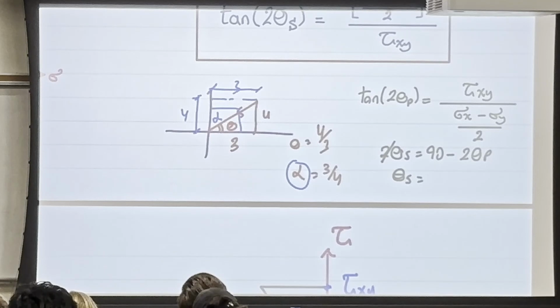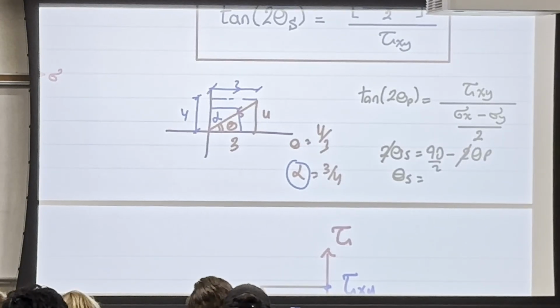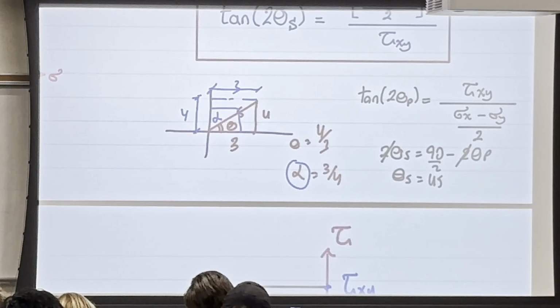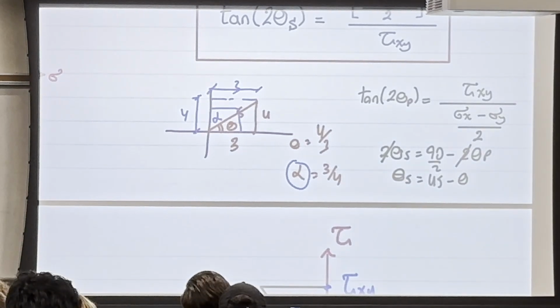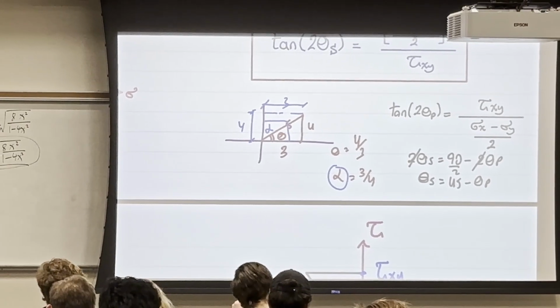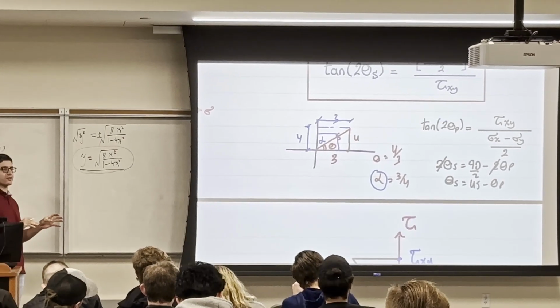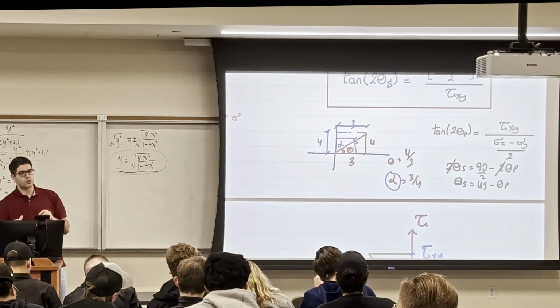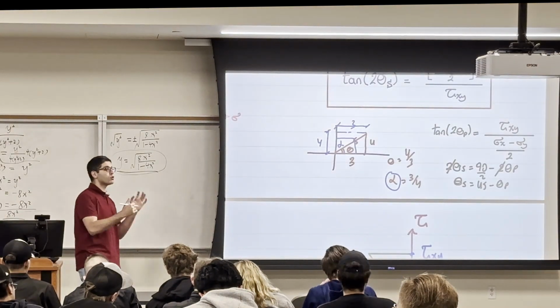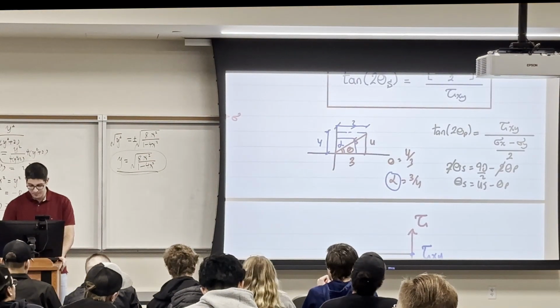So what I'm proposing here is that theta s is minus 45 minus theta p. Is that clear to everyone? Okay, a lot of concepts in this lecture. This is important just to prepare you guys to understand the Mohr circle, which we're going to discuss next lecture.